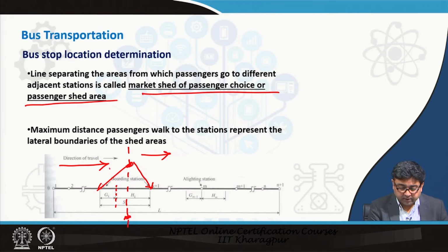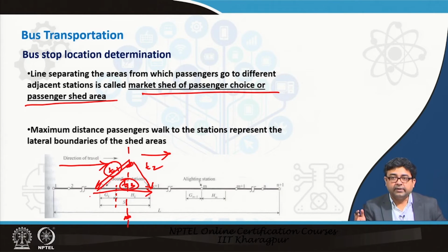Although these two travel times T1 and T2 may be equal, you would want to travel to k plus 1, because if you went to k, then again you have to get on the transit line. So there will be this travel time and this T3 that will be added on to your total travel time, right.